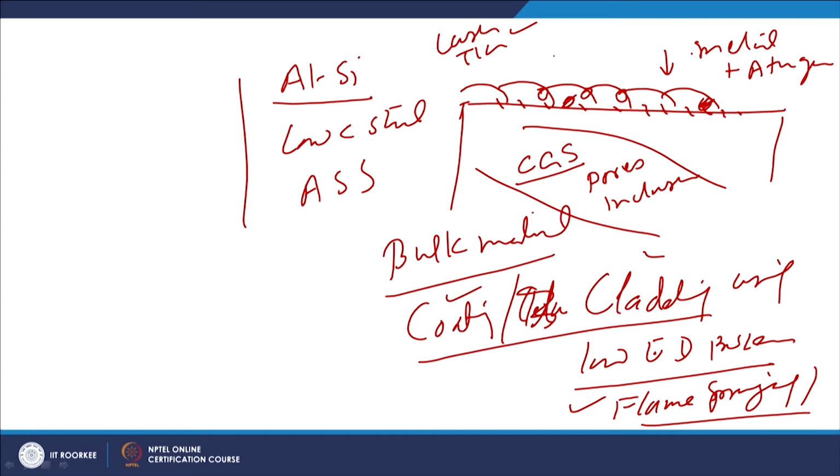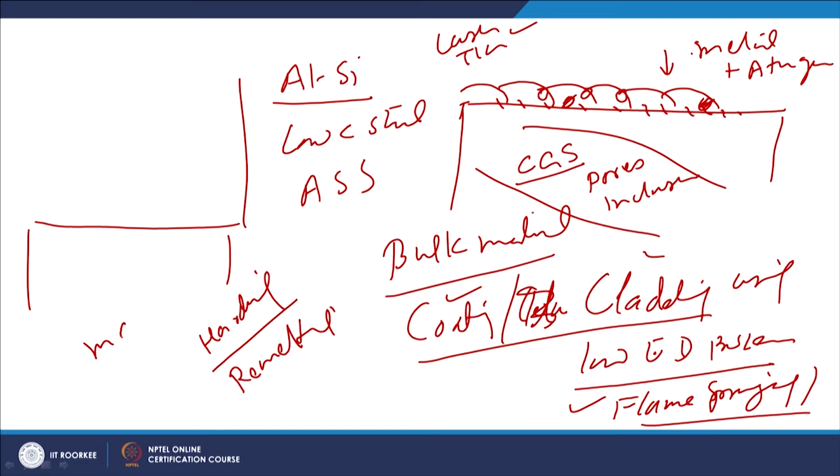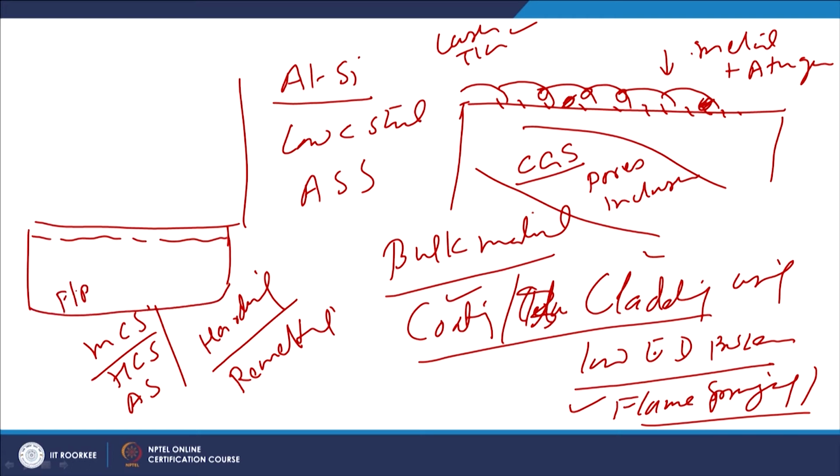So, definitely the grain structure refinement takes place, and if the metal is sensitive to hardening, then if we apply the remelting approach, apart from the grain refinement, like medium carbon steel or high carbon steel or alloy steels, if their surfaces are brought to the molten state, say these steels are ferritic and pearlitic. So, they have a mixture of ferrite and pearlite in different proportions.